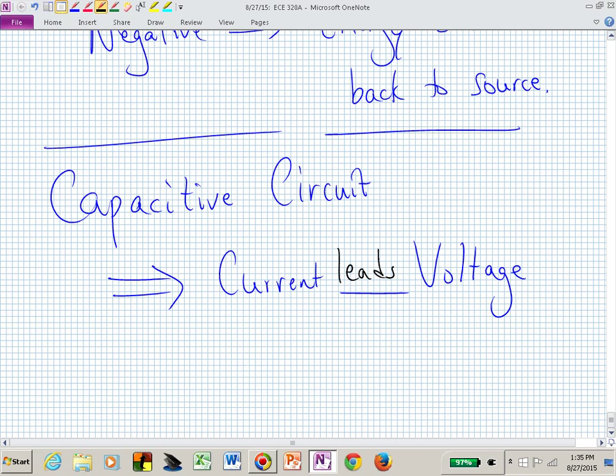You might have a capacitor bank, and you might flip some of those switches to make your plant look less inductive by putting capacitors in the circuit with your plant. And now you've reduced that reactive power that the power company sees from you. Well, that's a little bit ahead of the game, but that's where we're headed.